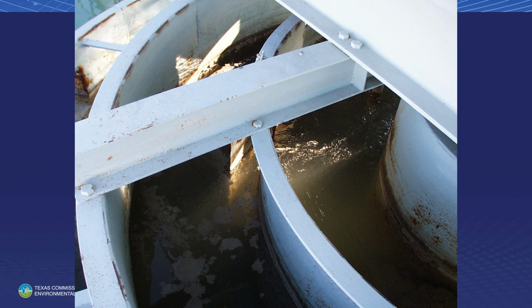This is what imparts the circular motion underneath the hood. The water, hydraulically coming out of that thing, comes out at an angle and starts that circulation underneath that hood. This is what gives it the mixing energy for your flocculation inside that upflow solids contact clarifier. And I've seen these things every which way, but they need to be set at an angle so you do get that stirring action.